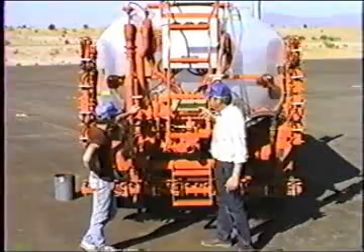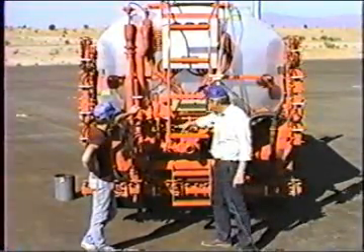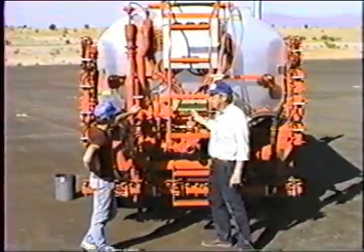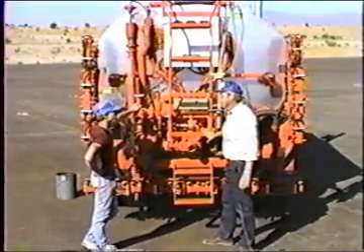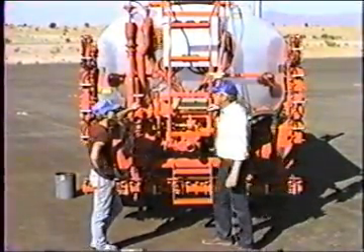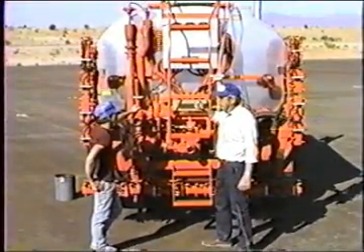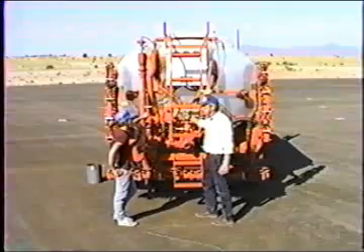So the important thing, anytime you're out of the truck and you assume that it's circulating, just glance at that and see that the rod is out. If that rod's out, it's circulating, everything's fine. How would you clean this out if that ever did? Well, if you're lucky, you'll catch it soon enough that by opening one section of the bar at a time, you can get very slow flow going and you can get it moving enough to circulate.